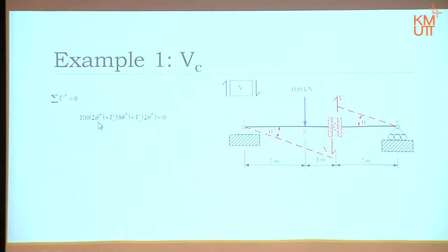Therefore, the term 2 theta appears here. That V, displacement down, positive. Okay? The left hand side shear, coming down from here to here. The total magnitude is that angle times the distance 3 meters. So 3 theta appears here. The force is down, displacement is down, therefore work done positive. On the right hand side, that one pushes up, the rotation goes up, right? From here to here is equal to theta times that distance 2 meters. Therefore positive, and then 2 theta here.